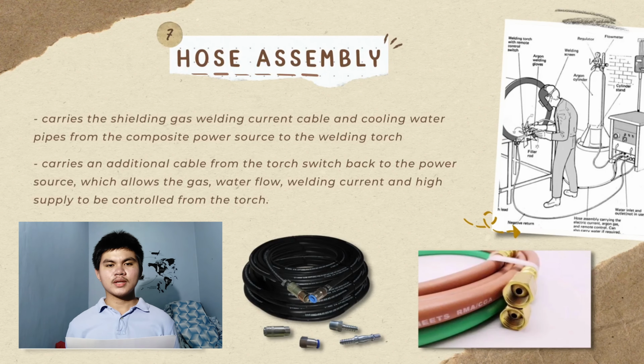Another one is hose assembly. This carries the shielding gas, welding current cable, and cooling water pipes from the composite power source to the welding torch. Cooling water is needed where high current is used, for example, 80% continuous operation with current over 250 amps. The hose assembly carries an additional cable from the torch switch back to the power source, which allows gas and water flow, welding current, and high frequency supply to be controlled from the torch.